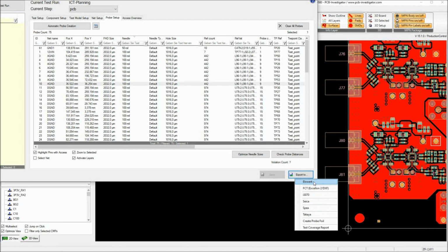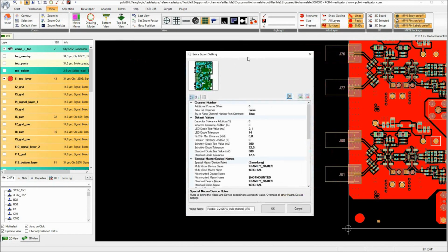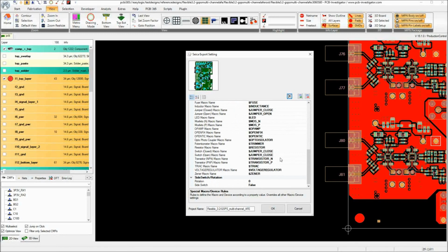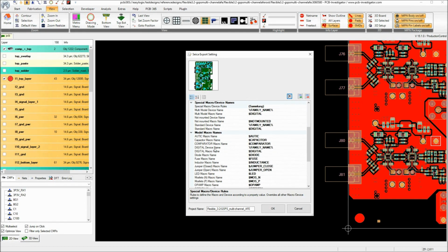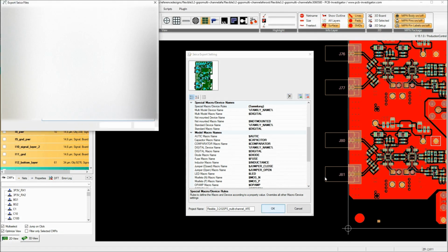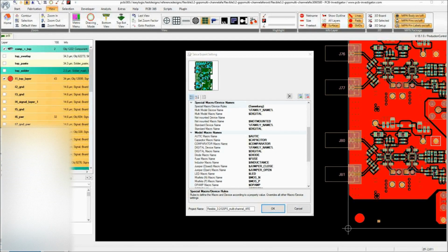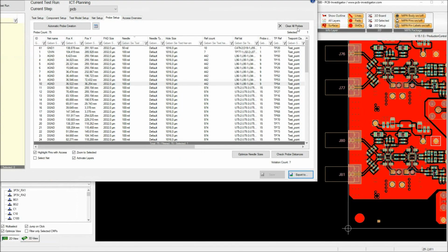And each of them, let's try for example Seika, has a different setting. These settings depend on the machine which you export. So this is a typical machine setting for the Seika. You enter these once and it's reloaded every time, but you can also export and import your settings or reset to default. There are a lot of values which are important for that machine. They are all described in our manual, and probably people working with Seika already know this macro and device and this system which Seika, for example, uses. Takaya uses something different, so the export settings dialog is always adapted to have the parameters of the machine which you are using. Then you say OK, you select a drive where you want to have it, and that's it. And the machine is exported.